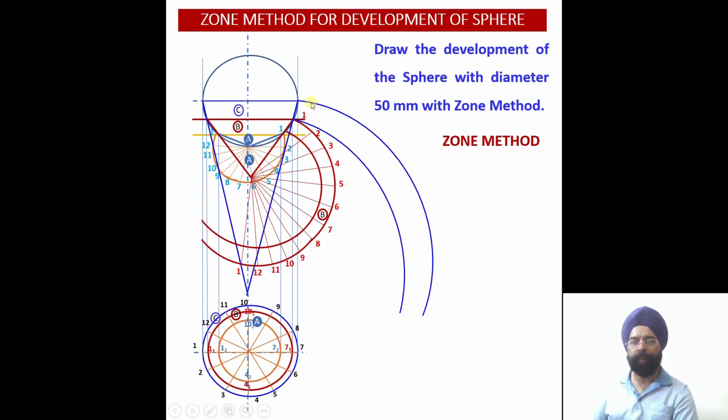So corresponding to the bigger true length, the outer curve is there. Corresponding to the smaller true length, the inner curve is there, just like we had drawn over here. Now, two curves have been drawn corresponding to the bigger slant length and the smaller slant edge length over there. Now, this point will be 1. This is this one over here.